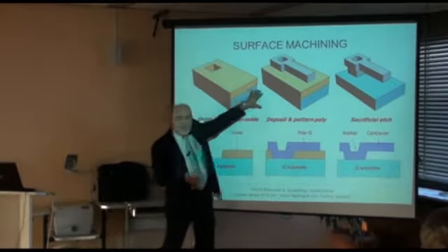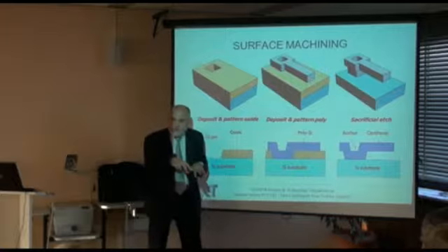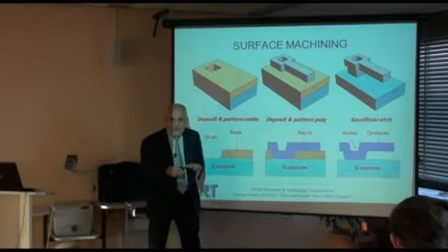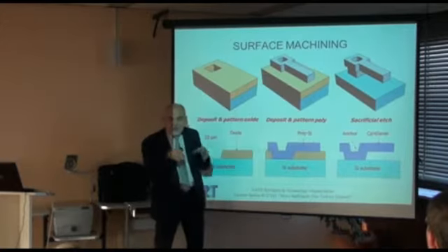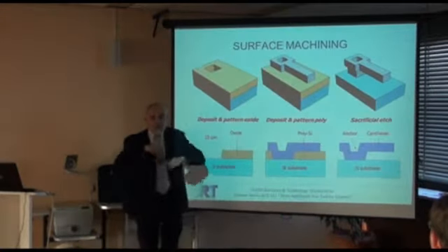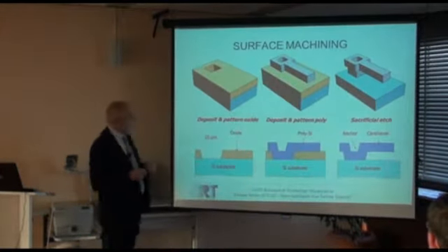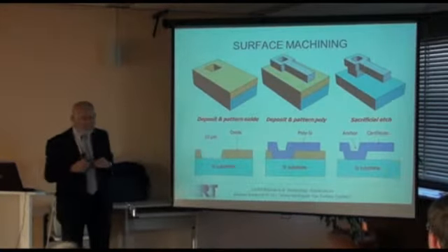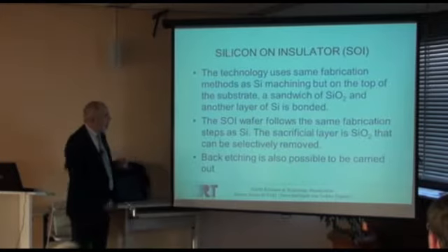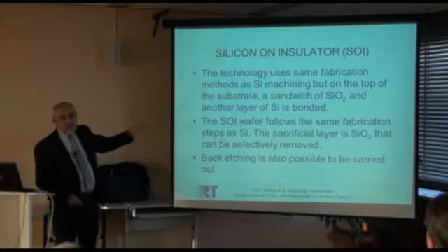Active components are always in the silicon. They're only one layer. All transistors and diodes will be within silicon, buried, and it's only one layer. I don't have multiple layers on that. And on the top I have resistors and capacitors, and circuits, of course. So that is the idea.